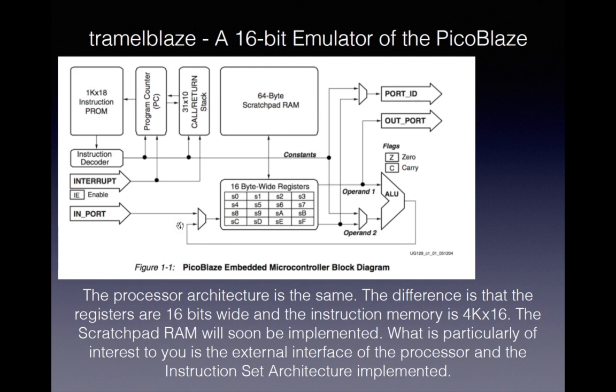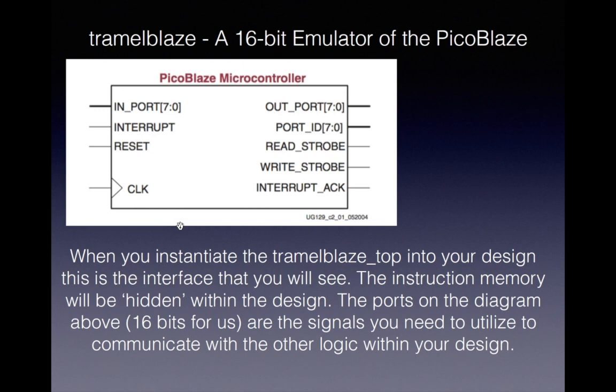But from this slide, what I want you to pay attention to is that some of these, port ID, outport, import, interrupt, those are the ports of the PicoBlaze that you will use to interface to the rest of your design. It's your responsibility to understand how these work.